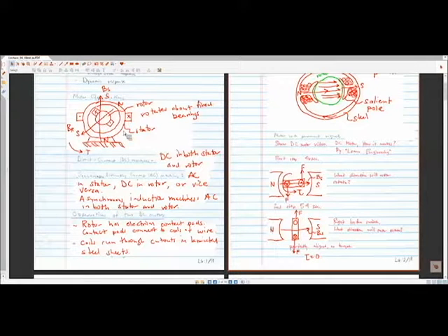And then each of these are going to either have, so the rotor almost always will have an electromagnet in it, especially for the brushed kind of DC motor. And the stator can have either permanent magnets in it or electromagnets. So either being coiled wire to make an electromagnet or actually putting in the elements of a permanent magnet into the structure. And the other thing is the commutator, right?